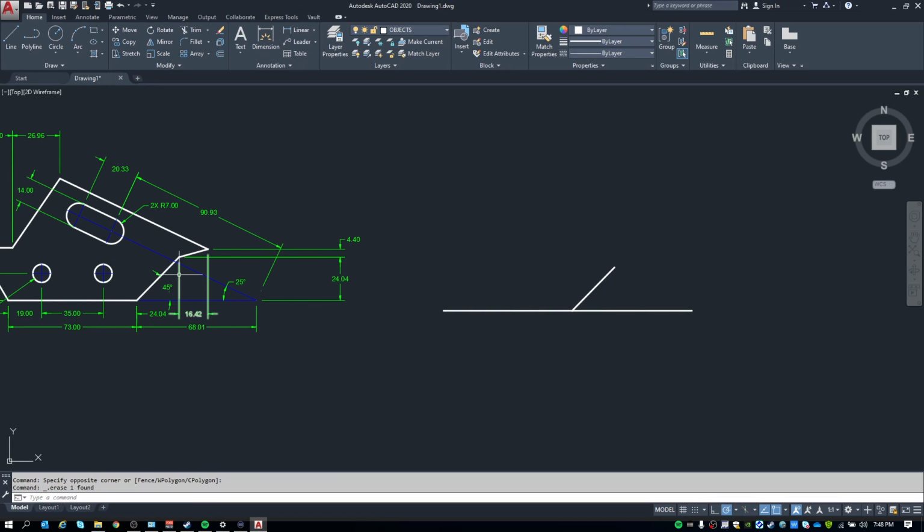For the next one, for this line here, there's not an angle provided, but we have the start point because it's already drawn right there. So all we need to do is identify where this end point is right here. Well, we have the X and the Y coordinates of that point. To get the X coordinate, we're going to add these two together. We need both of these.